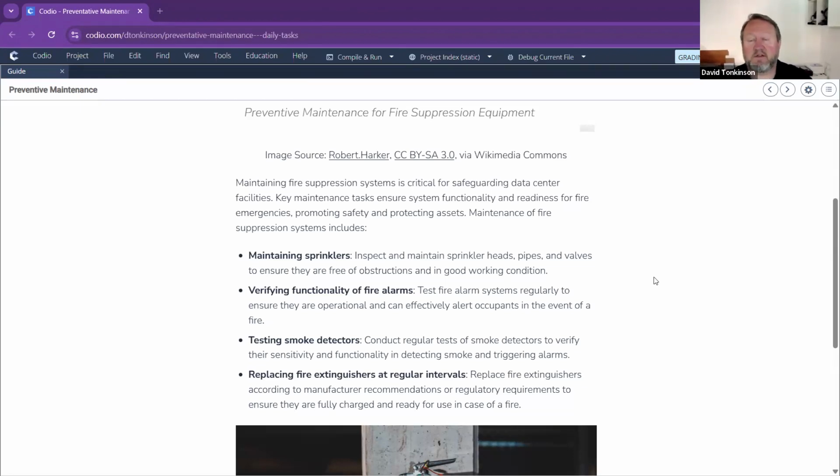You need to verify the function of the fire alarms. Yes, fire alarm systems can be tested. We can check each individual fire alarm point, you know, the magic ones that have break glass on them. There are test keys for each of those, so you can go around, you can test that, make sure it's working, see that it lights up the relevant part on the board, because they have fire alarm boards that tell you where the fire has basically started or where the fire signal has basically been sent off at.